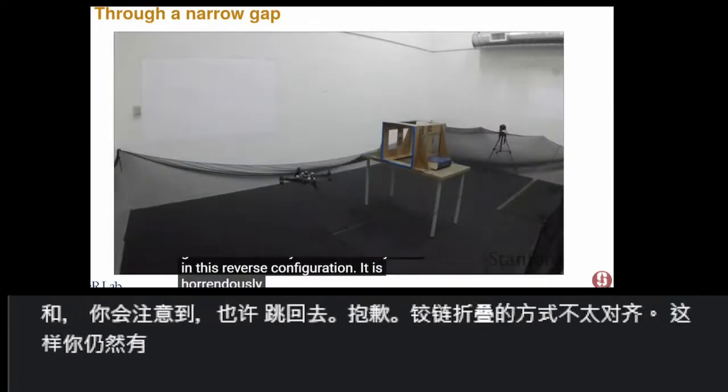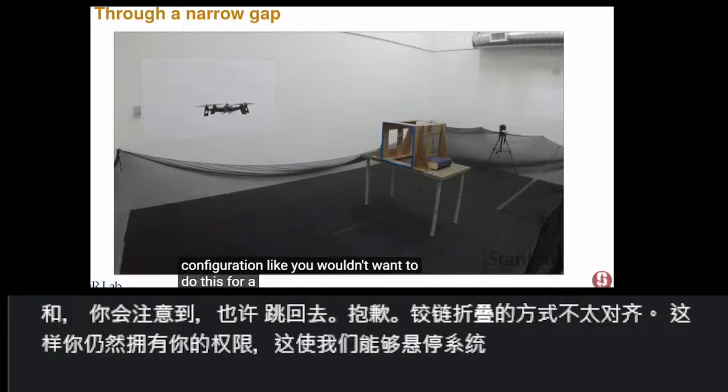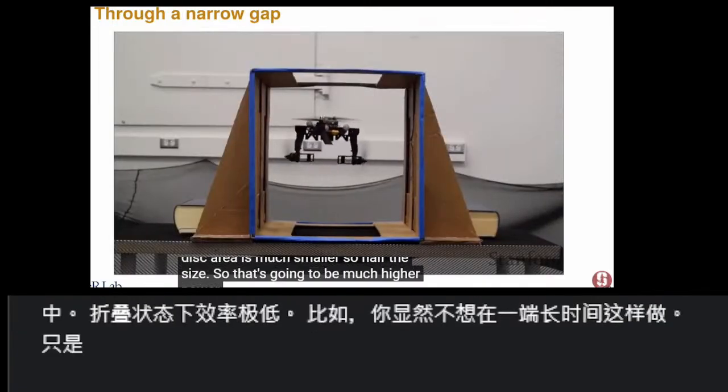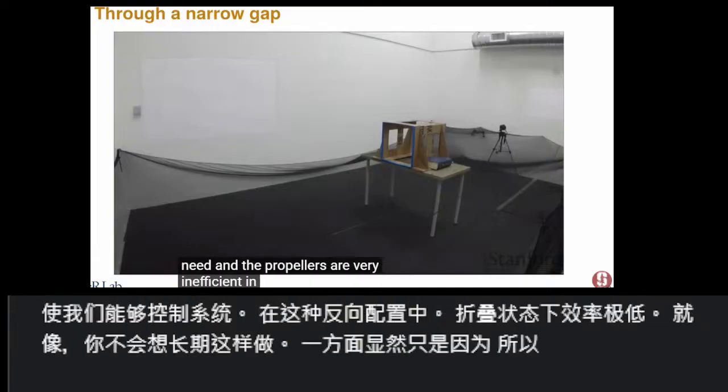It is horrendously inefficient in the folded configuration, like you wouldn't want to do this for a long time. On the one hand, obviously, the disk area is much smaller, half the size, so that's going to be a much higher power configuration. But also the yaw torque you need is quite high, and the propellers are very inefficient in reverse.